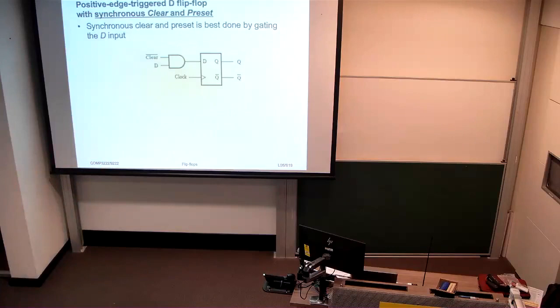Now that would be conditionally inverting it. It'd have to be an AND gate with an active low. So if you made this an AND and had not preset, then when preset is low, you're forcing that NAND gate, the output of the NAND gate, to be a 1, right? Are you convinced? I'm debating with one person here.